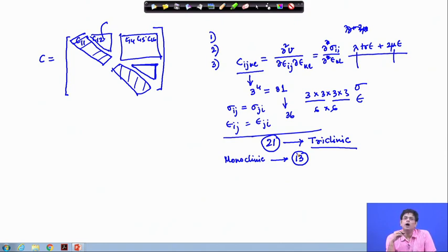So, the determinant of the rotation matrix is essentially -1. With one plane of symmetry, we find 13 independent constants, and how the constitutive tensor, or this C matrix, will look like, that we have also derived. Then we define a material which is known as orthotropic material,